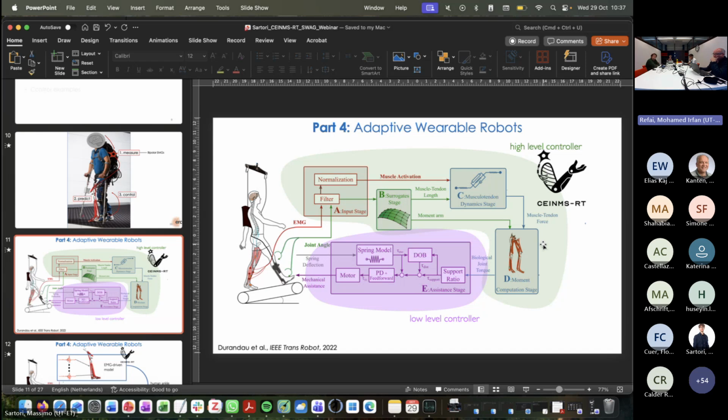So there can be some, not fully, it could be that the low-level controller will run faster than the high-level controller. So it will send basically similar values of torque in some time frames. But this doesn't matter because the low-level controller is running at way higher frequencies. So the low-level controller runs at about 1 kilohertz, whereas the middle-level controller typically runs at 50 to 100 hertz. So it's normal to have this difference.